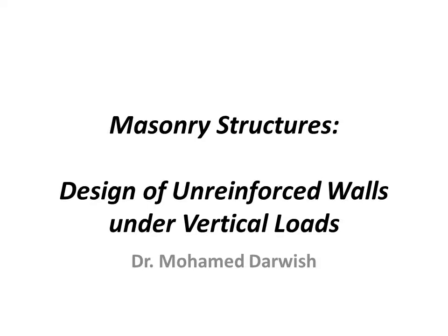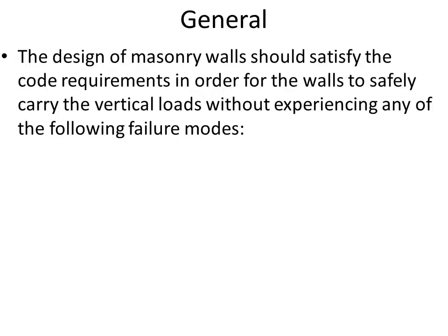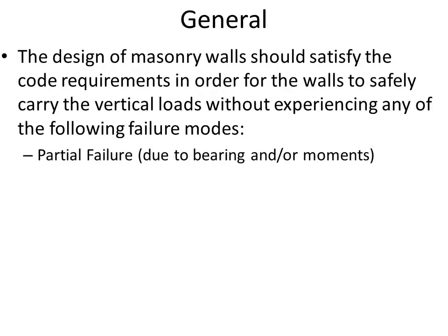Again, this is a lecture for design of unreinforced masonry walls under vertical loads. So the design of masonry walls should satisfy the code requirements in order to safely carry the vertical loads without experiencing any of the following failure modes. Our design here is based on several modes of failure. First is the partial failure, which is due to bearing and/or moments together.